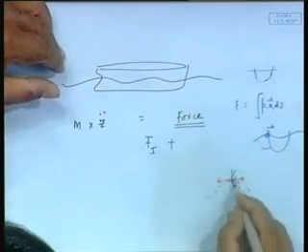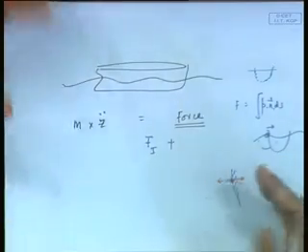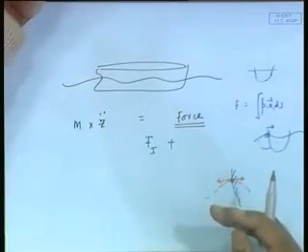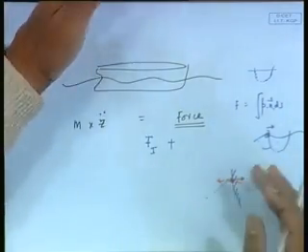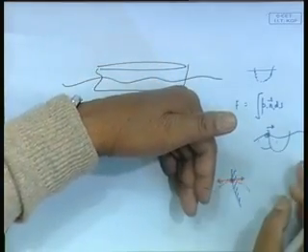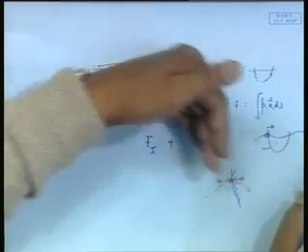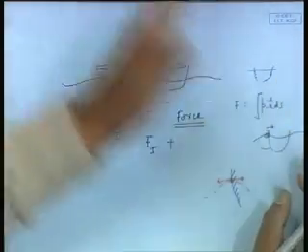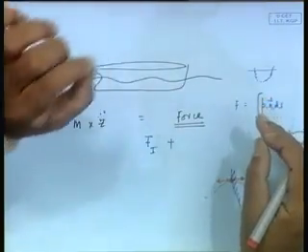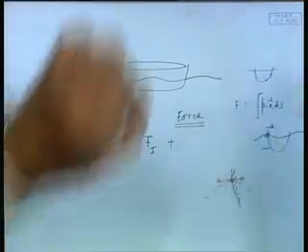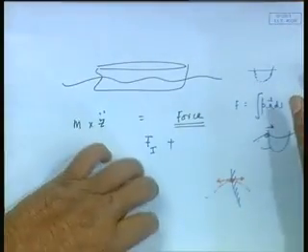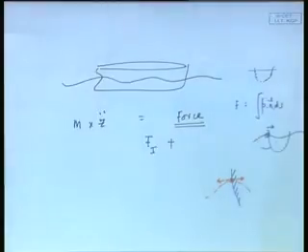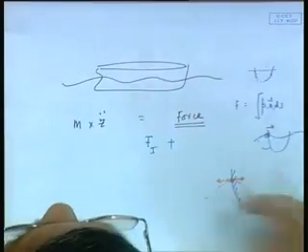So what is happening? This wave I call the diffracted wave, or scattered wave. It is like wave reflection. Similar to that, in hydrodynamics it is known as diffraction or scattering because it can be in any direction. This is the same thing as light coming on a particle and getting scattered. Similar explanation, you know why the sea is blue, why the sky is blue, etc. So there is a wave creation, so that the effect is 0 for this point.